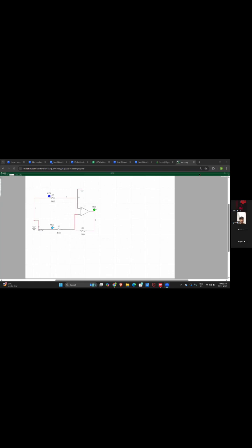And about the conclusion, the simulated differential amplifier circuit demonstrated the principle of common-mode rejection, producing almost zero output when both inputs are equal. This confirms correct design and theoretical operation. Such findings reinforce the value of differential amplifiers in applications where signal integrity and noise immunity are critical. The experiment highlights the importance of matched resistors and feedback for achieving reliable performance. And the circuit serves as an excellent foundational example for engineering students entering analog design. Thank you.